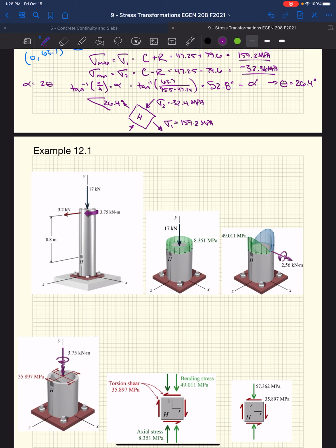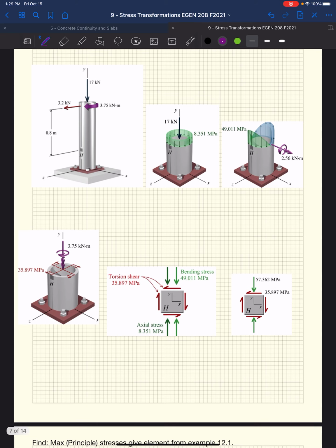It's got an axial load, basically the weight of the flag or any other elements hanging on it. And then for some reason, it's got a torque on it, right? You're going to stick with me here. So it's got a torsion on it as well. So we've got a lateral load, an axial load, and this pole is twisting. So we have all of these loading elements, axial, bending, and torsion, that are going to create stresses in our flagpole, okay?